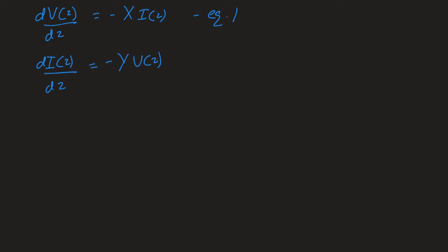Remember, we did telegrapher's equations for electric and magnetic fields also when we were doing Maxwell's equations and electromagnetism. These also link the voltage and the current, so they're coupled first order differential equations. How do we derive them? Well, we apply Kirchhoff's current law and Kirchhoff's voltage law on the transmission line model you saw before, and we did this for a lossless line and for a lossy line last time.